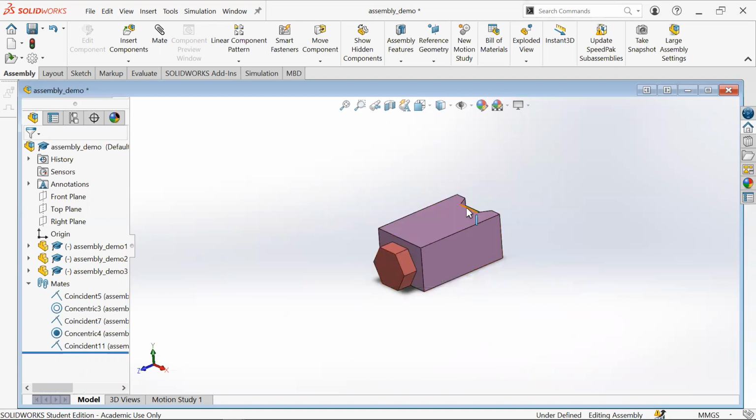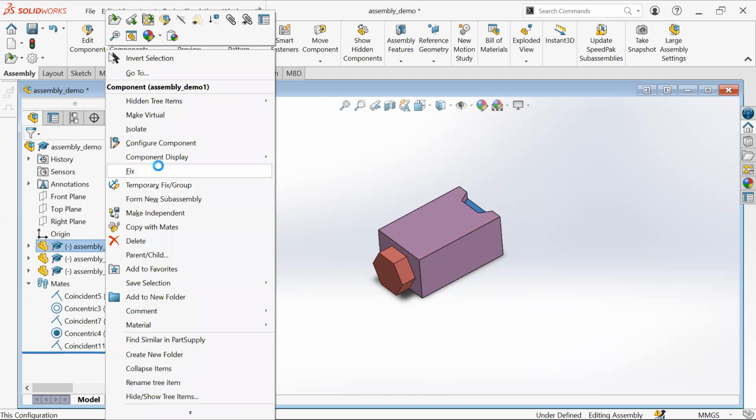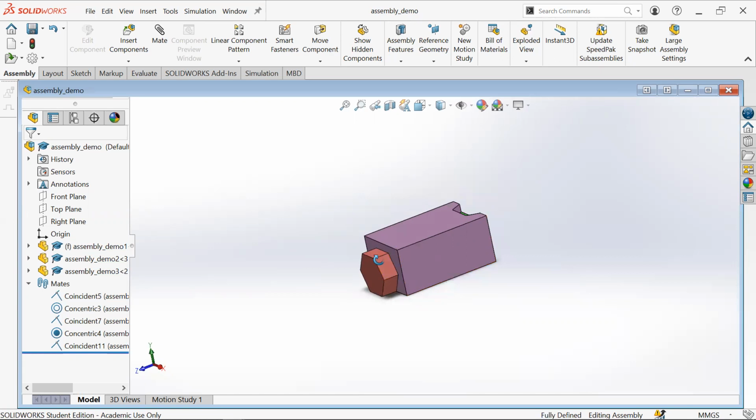You can see the bolt, you can see some of the green. Again, this is why we have an exploded view, because often you still can't see everything, even if your view is correct. That's why we have an exploded view, which pulls apart all your parts and displays them roughly where they fit in your assembly. So if you're satisfied with your isometric view, you right click again and you just fix. So fix and float, two opposite selections, two opposite effects.